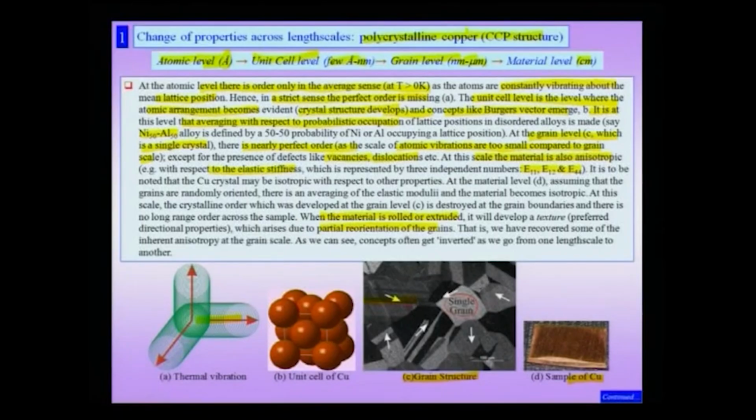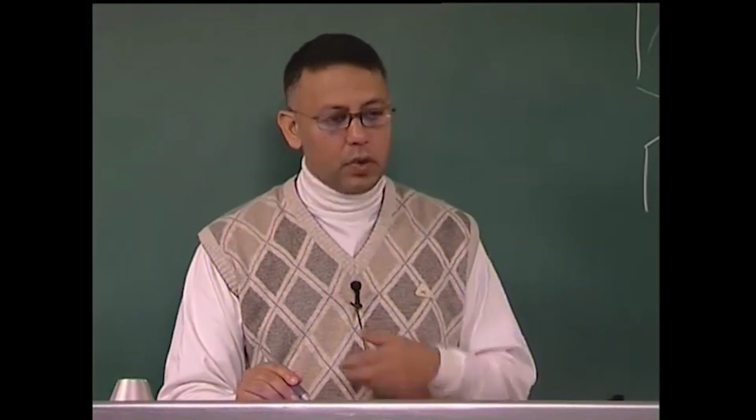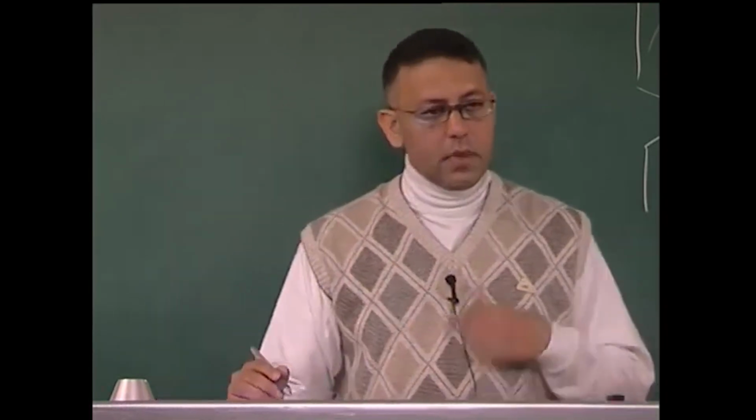of the grains, and of course the kind of texture which develops depends on the deformation process which has been employed. But now, in the presence of texture, the material again develops some of the anisotropy. In other words, we have retrieved some of the anisotropy which was present at the grain level. So, it is one of the crystallographic anisotropies which was present, which we have retrieved.